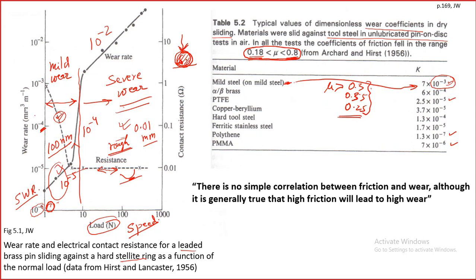So if both are mild steel, they are not good, they should not be used. Okay, so this is another design rule, that we should not use mild steel on mild steel. Even with lubrication we should not use it, and later we will talk about lubrication, how the lubrication actually happens, and why materials are so important even if you are using lubricant. So this is very important.